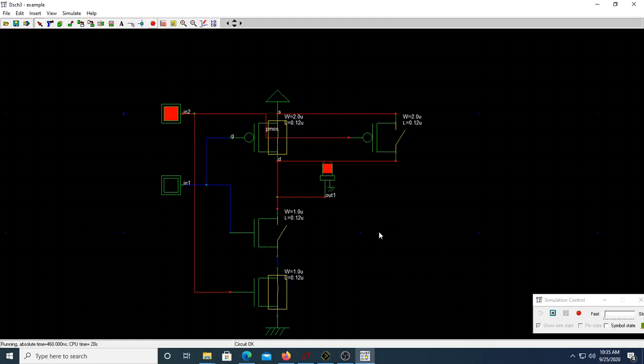And of course you can see the LED is getting the charge from this VDD through this transistor. If you make this the other way, then it is coming through this. If you make both of them 1, it is this. If you make both of them 0, it is still on because both the PMOSFETs are on. So this way you can play with this. You can implement any circuit over here. Okay, that's it.